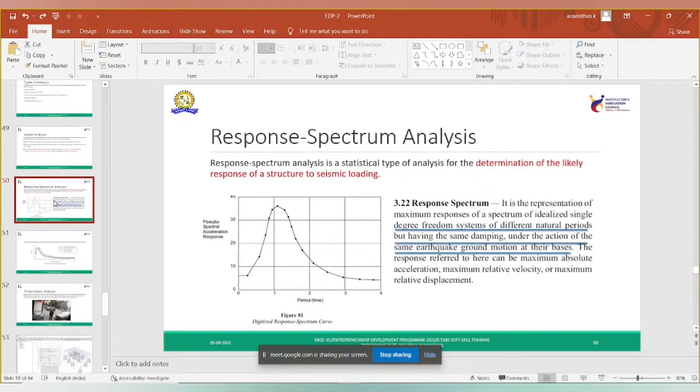First you should understand what response spectrum analysis means. Is it required to do equivalent static analysis and response spectrum analysis? If you ask that, you have to identify whether the structure is more than 15 meters in height or has irregularity. You have to check that. Even so, you can analyze a single structure using both the equivalent static method and the response spectrum method. For a single building, you can analyze using both techniques. There is no issue. Why? Because the software does that, which will give you better clarity on which method you can use for a structure.